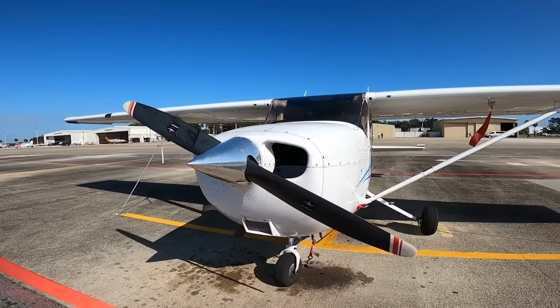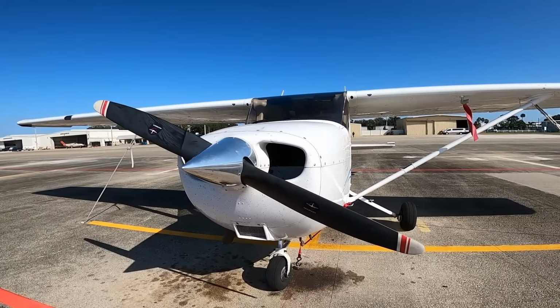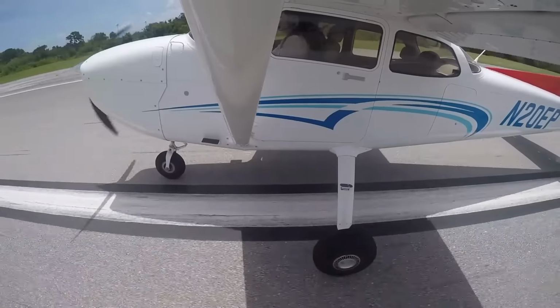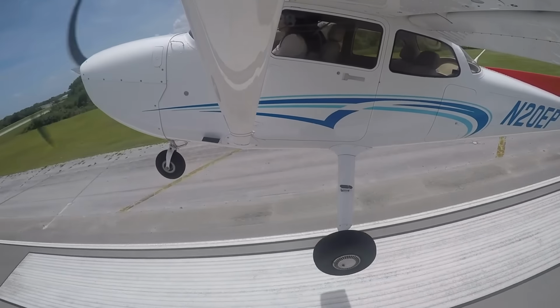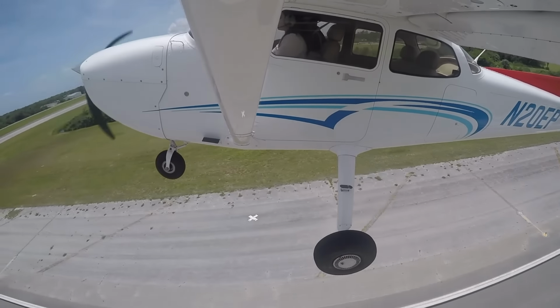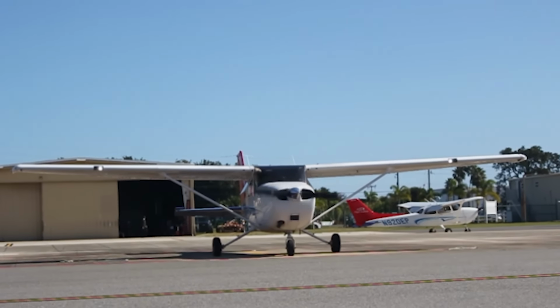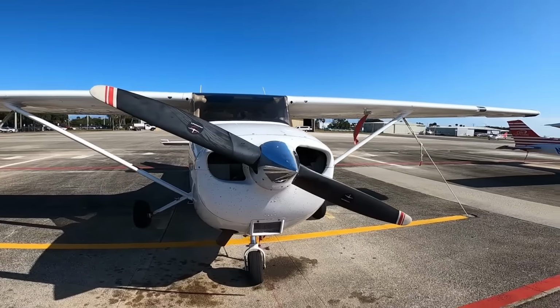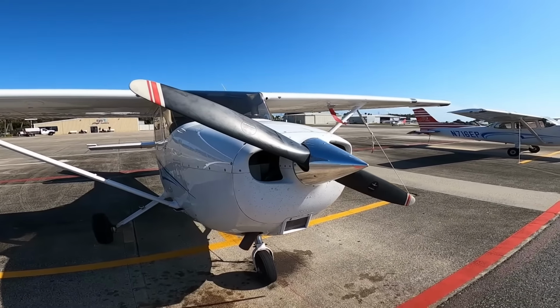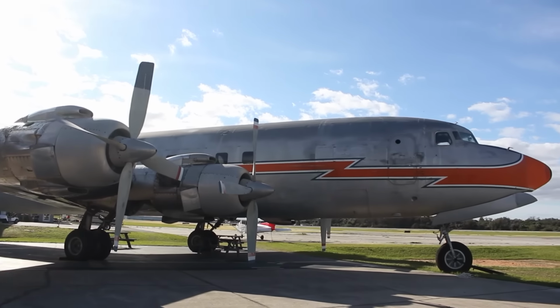A propeller is an aerodynamic device that converts rotational energy into force. This force propels the airplane forward. This creates thrust that is perpendicular to its plane of rotation. Propellers typically have 2 or more blades. Propeller blades are spaced evenly around the hub. They are available in either fixed pitch or variable pitch configurations.